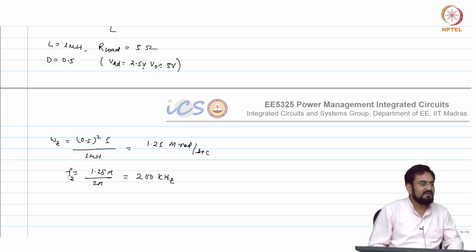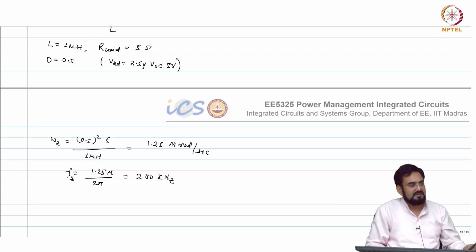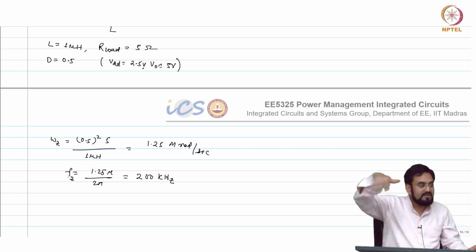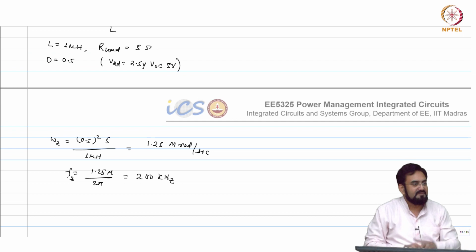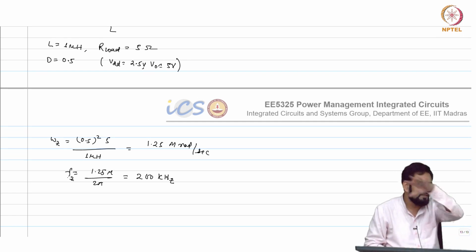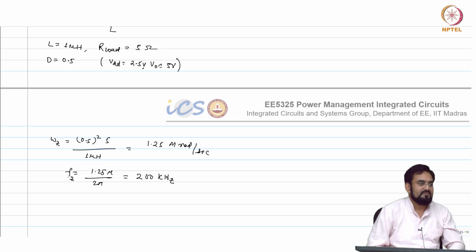Minus 45 degrees. If you have 60 degrees, then it will drop, and it will reshape your frequency curve also. So your omega UGB will ultimately be pushed higher because gain will increase, so it will make it even worse. Correct?